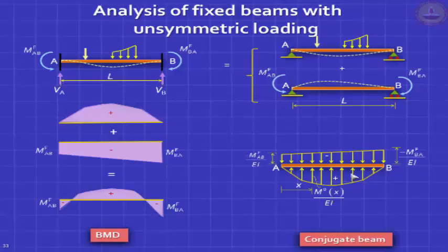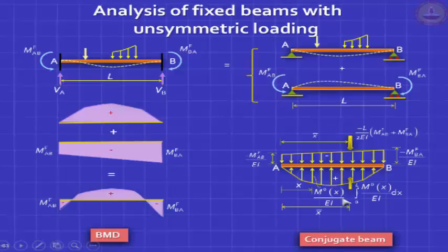What are the two equations? Well, firstly, this is a free beam. It's hanging out there. It's self-equilibrating. So first, the areas must match. This top area must be equal to the bottom area. You must know how to calculate areas. Trapezium is easy to calculate. This will depend on the loading. Not only must they match, moment equilibrium should be satisfied. The lines of action must also coincide exactly. You've got two equations.